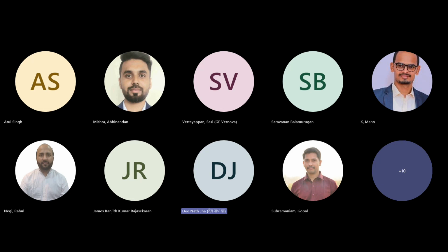The impact assessment was done using decision trees, and on top of that, for correlating all these models, an analytical hierarchy program, AHP, was used, and normalization was done using the Johnson transformation. The software for data storage was ERP, and the SCADA data historian was used to extract values from the SCADA system. That was the software part. For the photogrammetry and 3D models, we are still in process. We have done some pilot projects for a couple of transformers. In one of the projects we used Navisworks, and in another pilot we used photogrammetry.